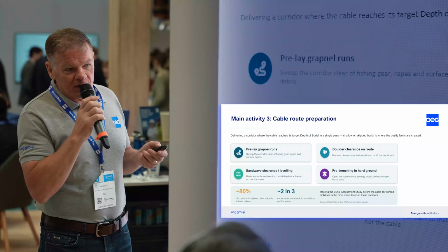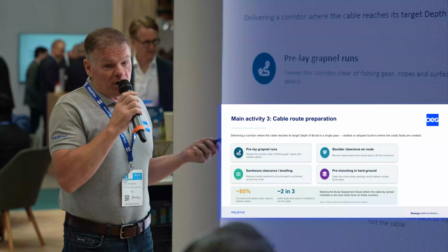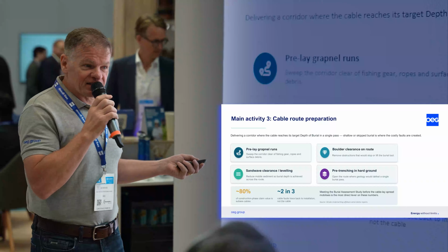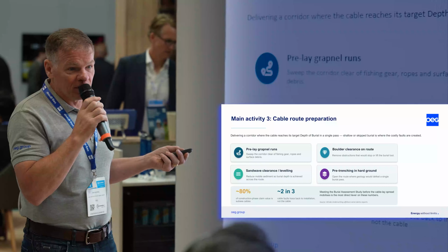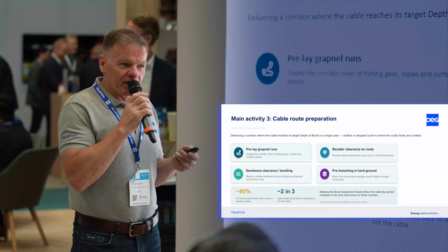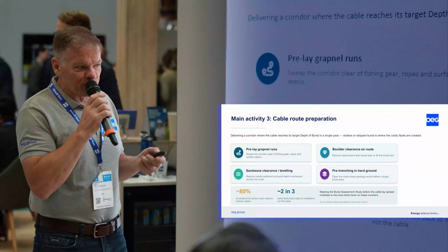So where you may have a buried cable, for instance, that sand wave can actually debury that in the space of 6 months, the whole length of the cable, and cause a problem. Hence why now they are looking to bury them deep, especially in these moving sand areas.